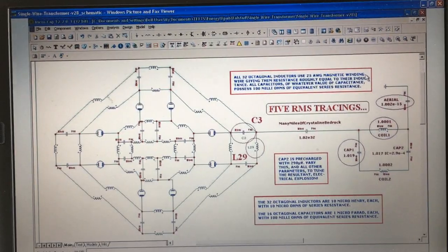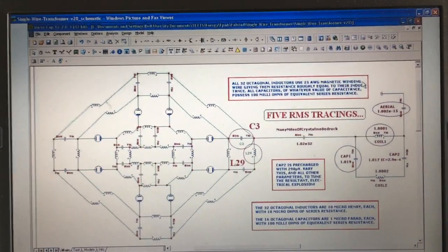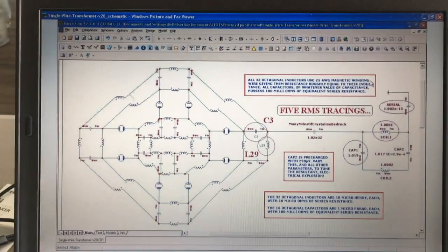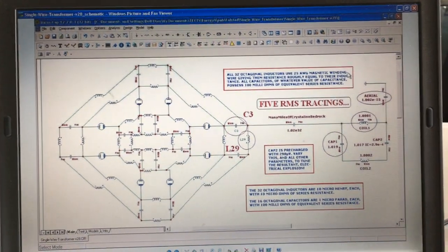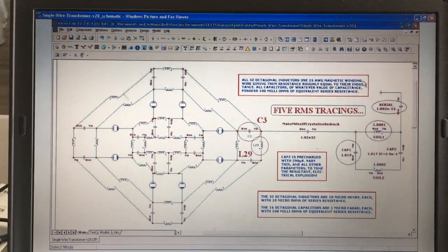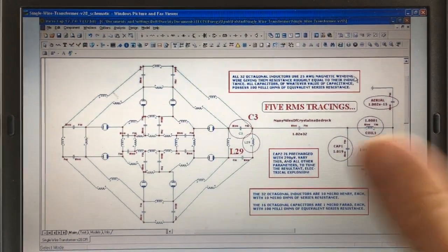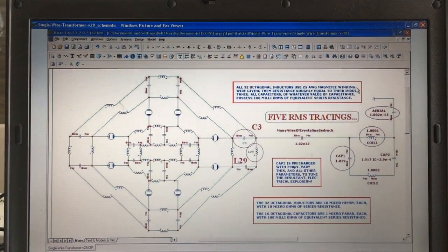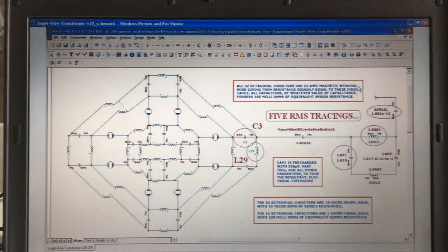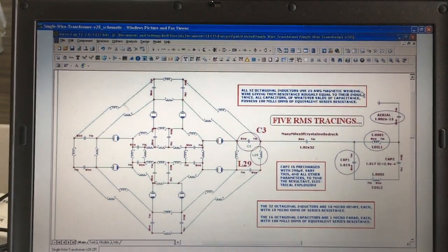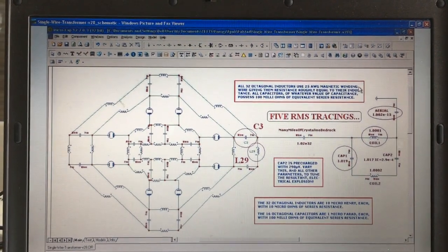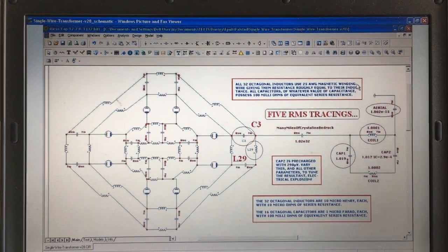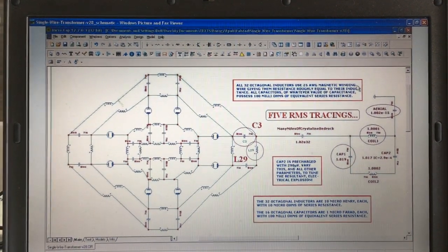Now, in the real world, when they are fabricated, there's always slight deviations, so you don't have to worry about it. But in the simulator, you've got to worry about it, because they use floating point arithmetic, namely what I would call scientific notation, but whatever you call it, you only have so much accuracy, so many digits to the right of the decimal point, and I think it's one digit to the left, and then it'll be to the power of something, e to the 10 or e to the negative 20, whatever it happens to be. You start losing accuracy when the value of the number starts to become excessively large or excessively small.